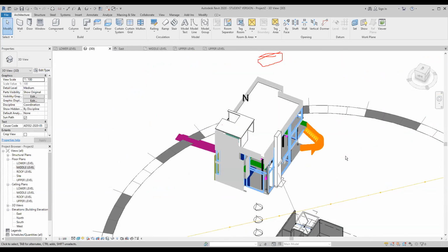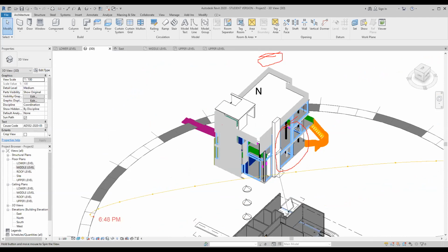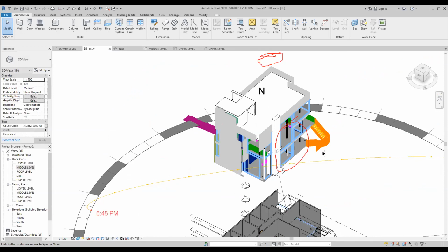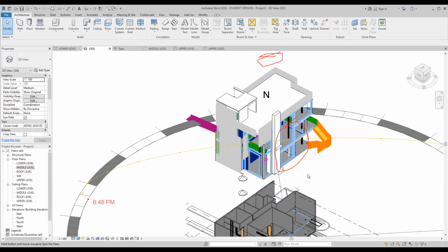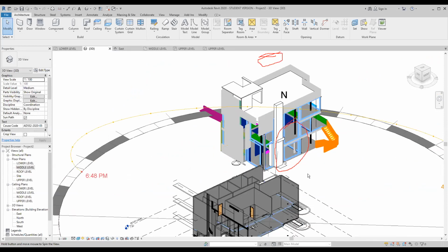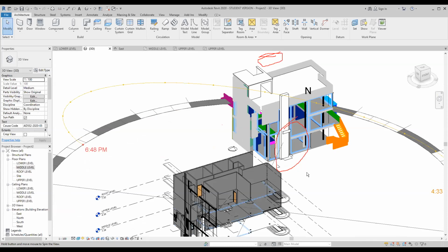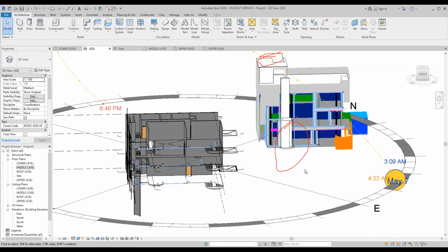Okay, good. Just in this area, please just model walls. Keep them as a wall. Don't model this glazing, because after that we will change those walls to what we call curtain walls. So don't keep it empty on this side. Make it a wall like other walls. And after that, we will change these parts to glazing. This part and this part.